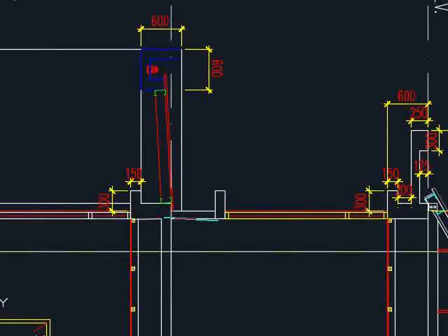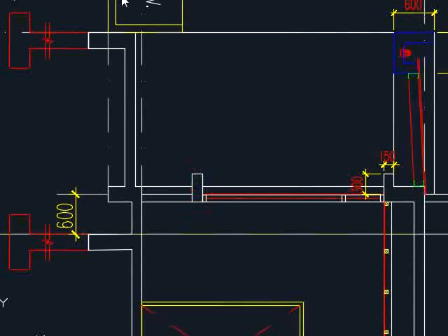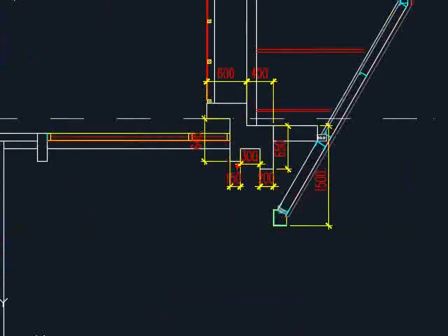And for the 2 layers of reinforcement here, it needs to be properly embedded inside the beam with a minimum anchorage length. Same goes to this fin. Most likely it's going to attach together with the beam here, and you have a wall which is reinforced, and there are reinforcement bars continuous to ensure this part is properly reinforced. And you know that this one, it will behave as a cantilever. That means you need to provide top reinforcement bar on top here. This is another one.